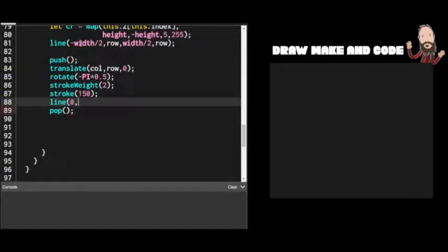And let's draw that line. I'm going to draw it at X. I'm drawing a vertical line, and then I'm rotating it into the Z. Because I don't really have a Z coordinate that I can draw a line to, because it's X and Y. That's all you have with line. As far as I know, I don't know that it works with Z. So you can use the X and Y, just draw that where you need to, and then rotate it into the dimension that you need it to go into, which is typically the Z.